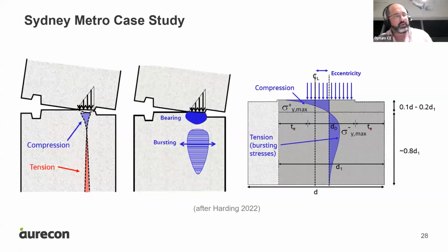What happens is that even during construction, when you're erecting all these segments, there are obviously tolerances, and we never build a perfect circle. So there's always a tolerance in some rotations where these joints might not be perfectly aligned. They might be slightly rotated right from the start. And also with the loads, because these joints are pure contact of concrete to concrete, right? We only temporarily use bolts to hold them together that are removed later. So once these joints try to rotate, you can imagine that upon groundwater loads, rock loads, soil loads, whatever loads are applicable there, these segments will tend to rotate, and you have these highly concentrated forces in localized areas, which will put your concrete in compression really close to these loads, and in tension when it goes down into the segment thickness.